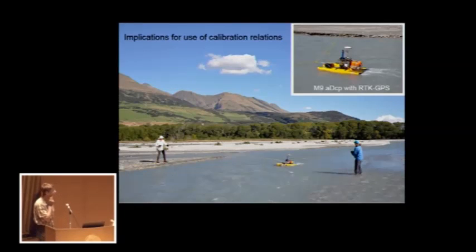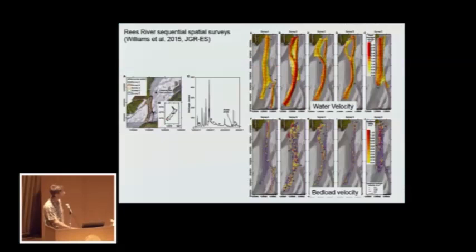Okay, so what are the implications of this? Like I said, I'm always interested in doing spatial distributions. Here's an example of us doing a spatial survey across the main Anna branch. So we basically just drag the boat back and forth in really tight sections and collect bottom track data as we go. And this produces maps like this.